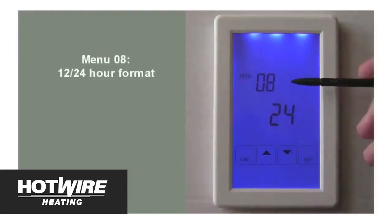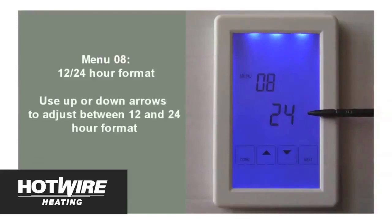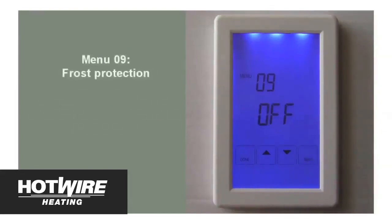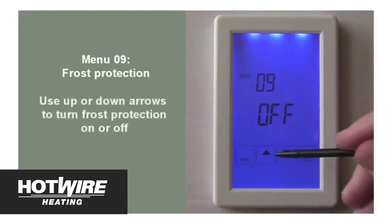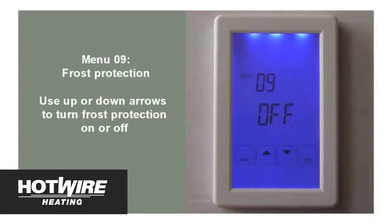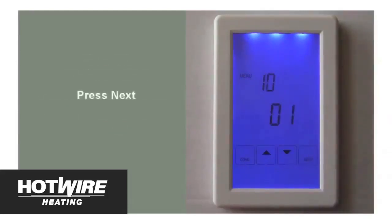Menu 8 is used to adjust the clock between 12 and 24-hour format. 24-hour format is the default option, but in this case we will change it to 12-hour format by selecting 12 and pressing Next to move to the next menu. Menu 9 is used to turn on frost protection. When this option is turned on, your unit will not allow the floors to fall below 5 degrees Celsius. This is handy in locations where the floor temperature can fall below freezing. In this case, however, we will switch it off, and then press Next to move to the next menu.